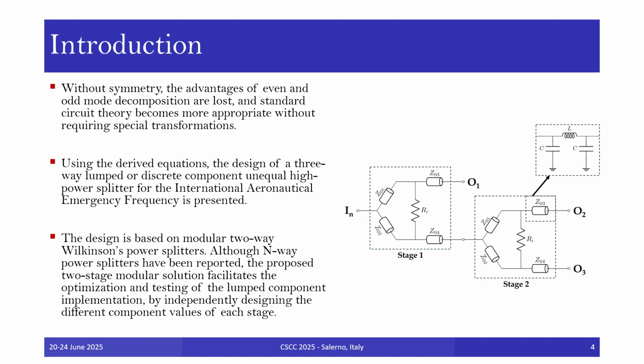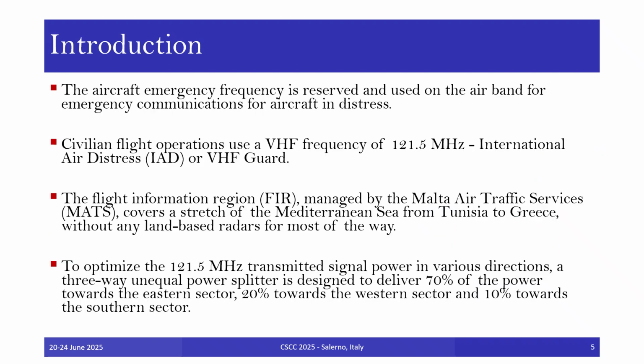the International Aeronautical Emergency Frequency is presented. The design is based on modular two-way Wilkinson's power splitters. Although N-way power splitters have been reported in literature, the proposed two-stage modular solution facilitates the optimization and testing of the lumped component implementation by independently designing the different component values of each stage.